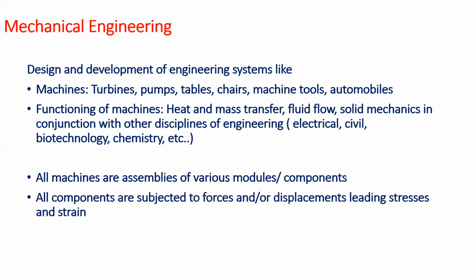And all these functions, all these components are subjected to either forces or displacement, regardless of whether it is intended to take loads or not. For example, if you consider the case of the electrical wire again, there it was not intended to take any mechanical load. Usually it is clamped to its surroundings. But at the same time, due to the heat flow in it, there will be thermal expansion and there will be thermal stresses.